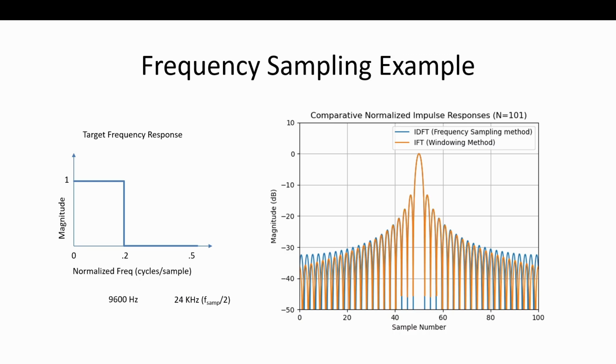Remember, the windowing method is to get yourself an impulse response as a continuous time domain impulse response. Well, if you put in 1,000 samples here, you're going to have 1,000 samples in time. So you're stretching time way out. What you're doing is moving this corner, where it would fold in on itself, further and further out. You can picture that? So you're minimizing the time domain aliasing.